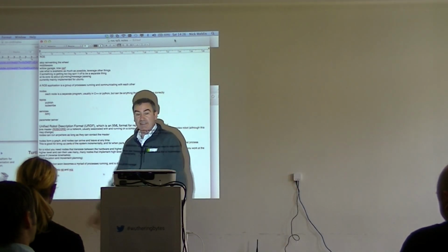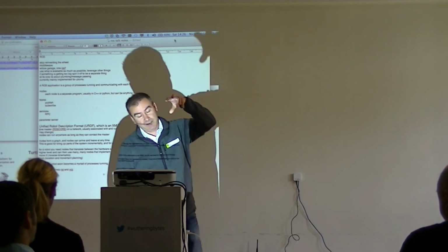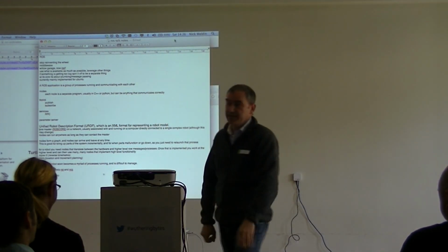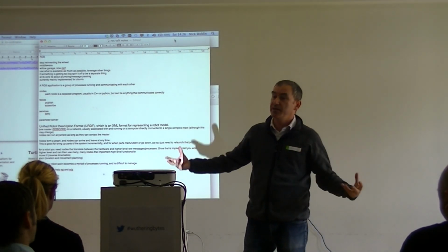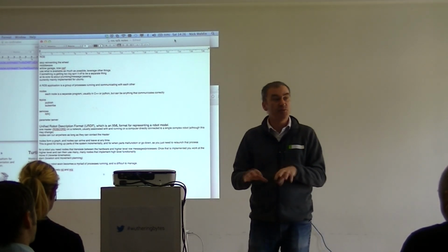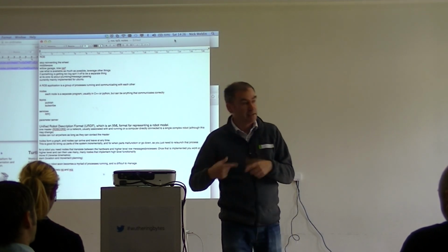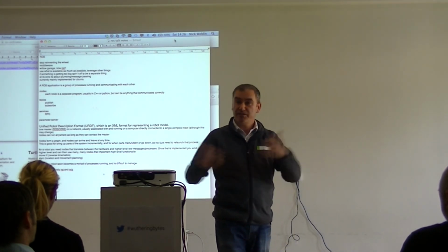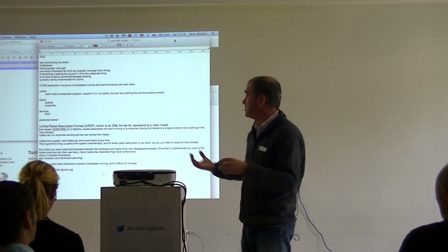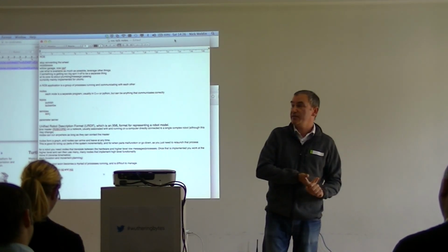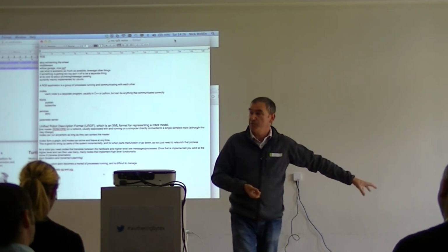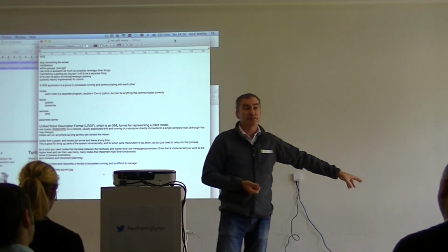It's network based, so once you've got a ROS core running on that network, any computer that can see ROS core can run nodes. So you can develop stuff on one computer, and if it starts to get too difficult, you can float stuff off to other computers very easily, because a lot of the path planning stuff is hugely computer intensive. So you don't want that running on the robot, because your batteries will die very, very quickly.